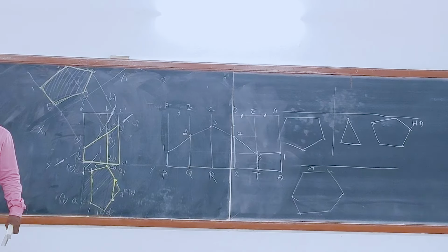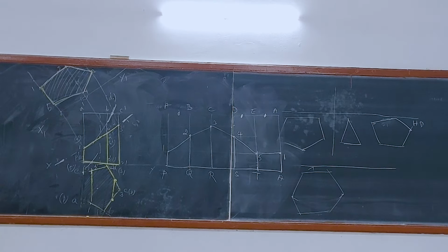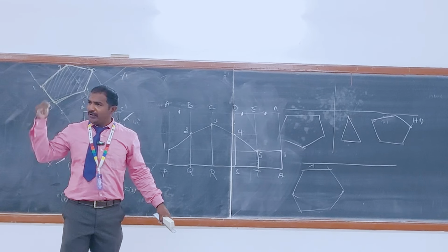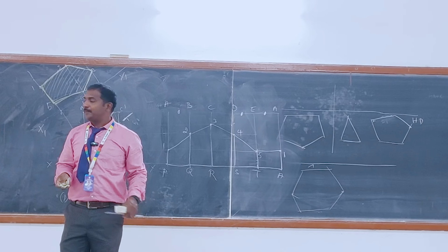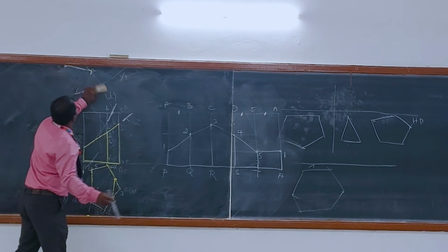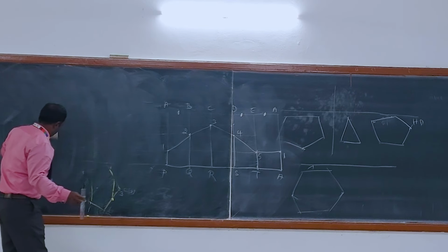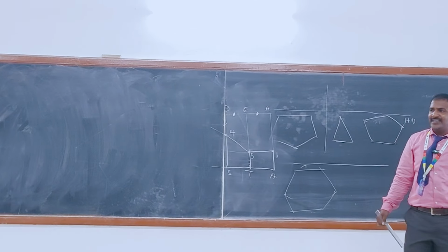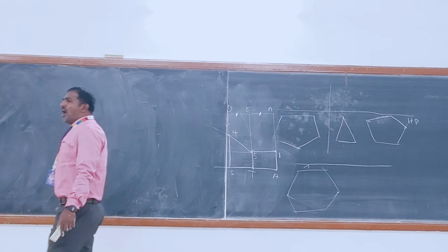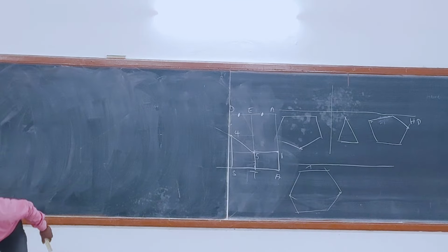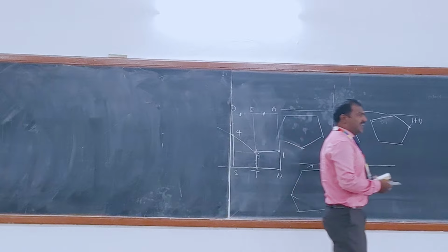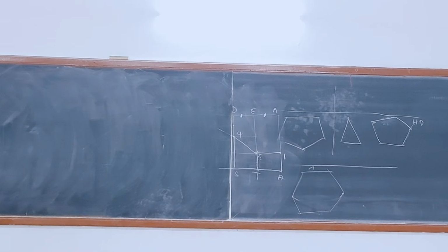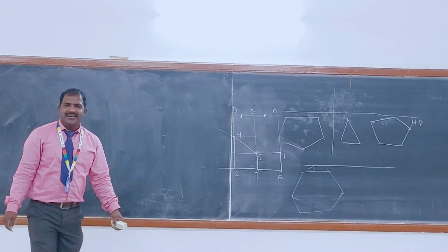Then we move to the pyramidal form. Okay, write it down. Let's try a rough attempt, about 5 minutes; there is no time. Same, we go for a pentagonal pyramid of base side 30 mm, axis height 60 mm, resting on HP on its base, such that one of its base edges is parallel and nearer to VP.